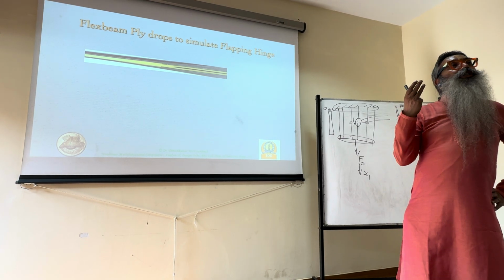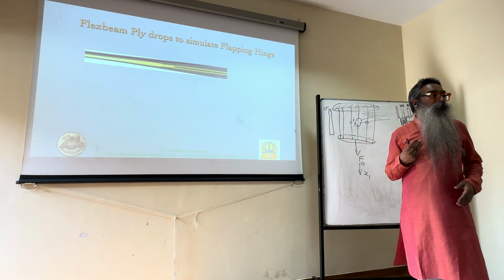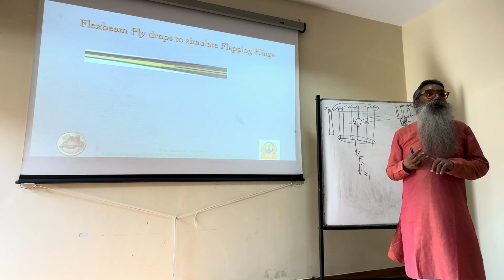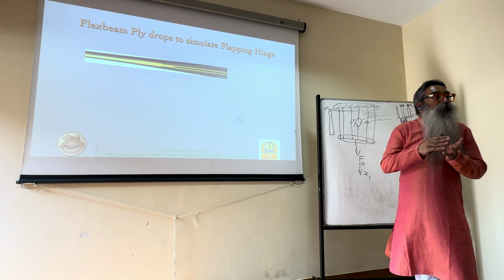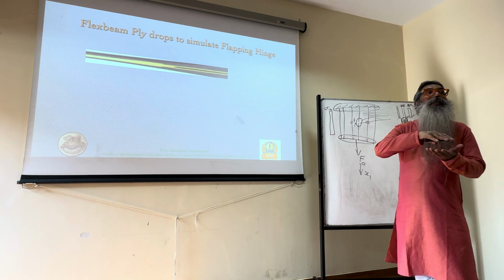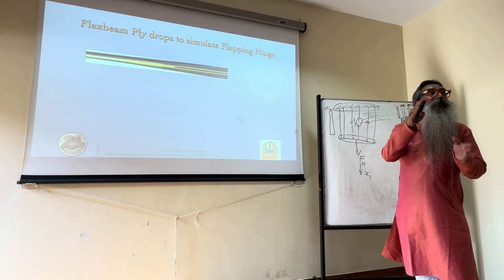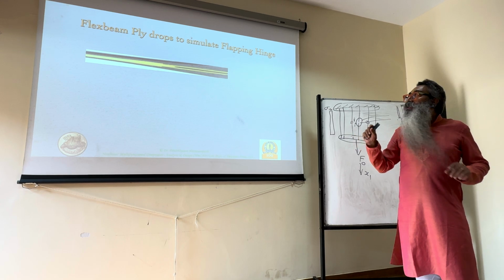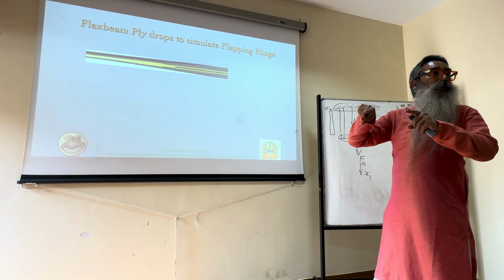Remember the triple functions we talked about when we were talking about any aerospace structure. All three of them led to the conclusion that you move them outwards, it's better, right? That's why we said I section or thin circular tube are good for bending and torsion respectively. Here it's just a rectangular cross section, right? If I cut through this, it's just a rectangular cross section, okay?